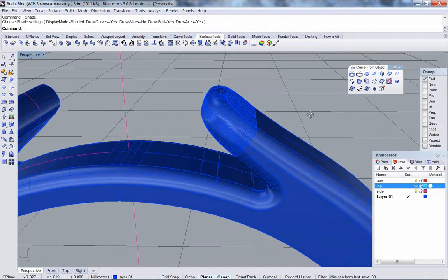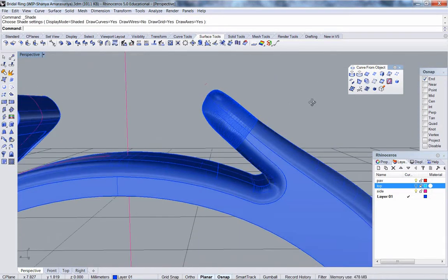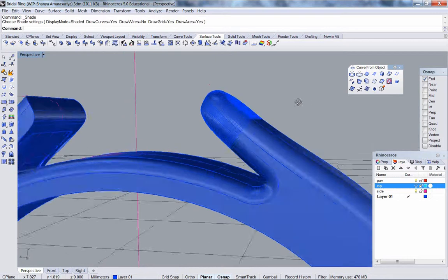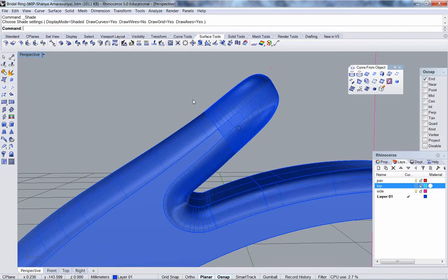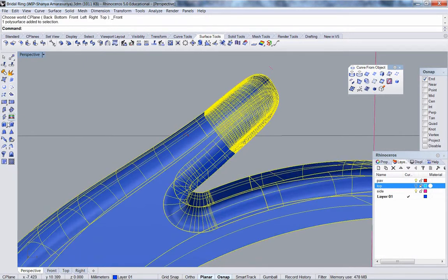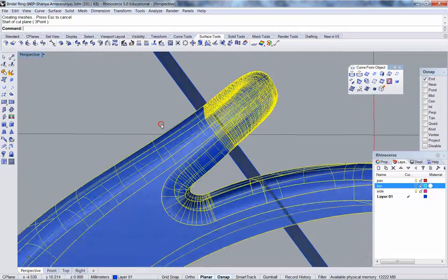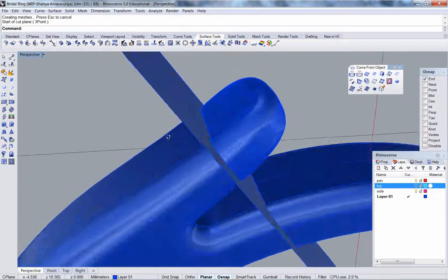What would the solution be? Blend surface. Okay. The solution would be, how did you cut this off? Did you use a cutting plane like I did in the tutorial? I think so. I think so too. So the solution would be to come back in here with a cutting plane. That should cut right along where we want it.